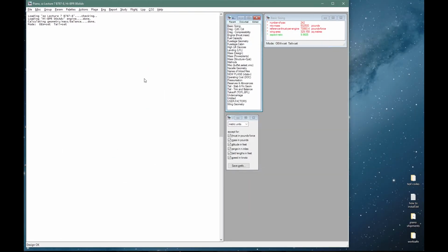The development of the Dash 10 took several years and relied on experience gained from both the Dash 8 and the Dash 9. For example, one judgment made by Boeing was to not include the original planned wing extension, which kind of relates to what I said earlier about span in the context of optimization. Many unknown details about trim and balance and tail geometries can influence the best choice of wing location, or in other words, the split between fore and aft fuselage plugs. We will simply take the published gross changes in geometry and certification weights directly from the Dash 10 specifications in the March 2018 ACAP. So I will now implement these changes.